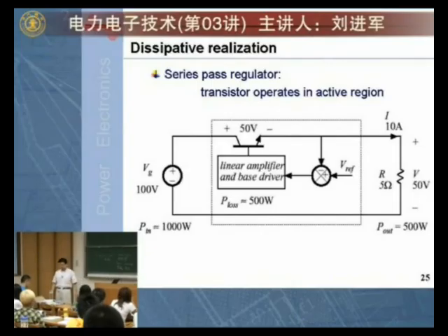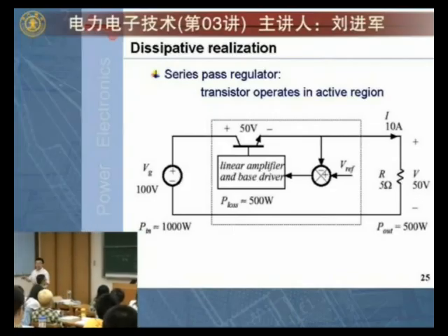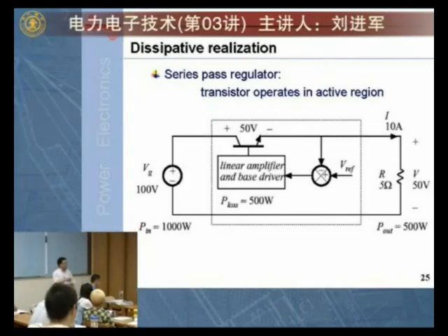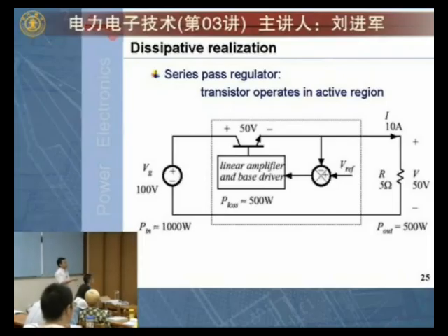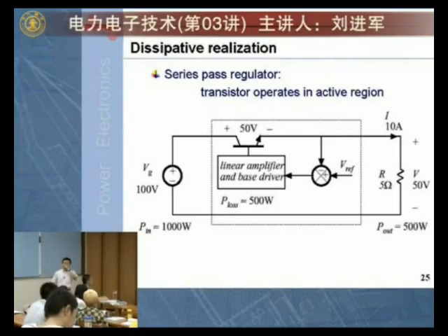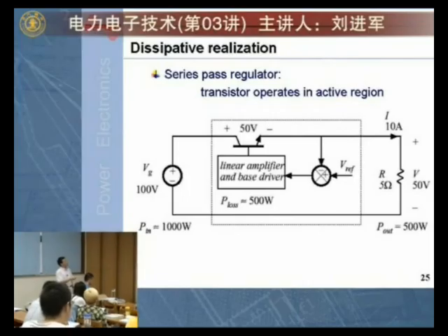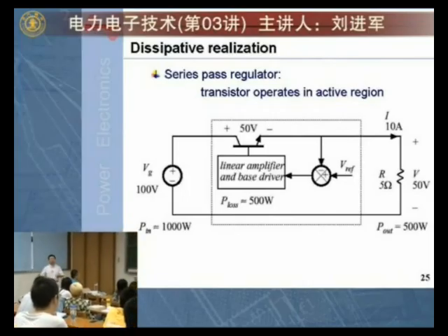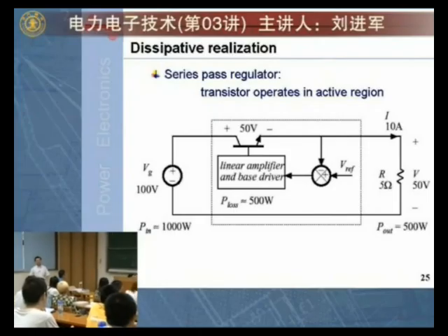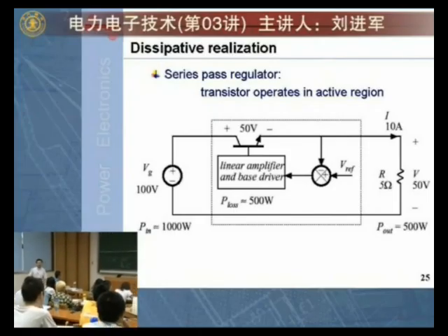Okay, so by the second solution, we can realize automatic control and we can deal with disturbances. Even when this load resistor is changed, and therefore the load voltage is changed, either smaller than 50 volts or higher than 50 volts, even when that happens, I still can measure that and compare with my value of commanding. And therefore, I can change the current flowing through so that I make sure the load voltage is coming back to 50 volts again. So that's exactly how to deal with disturbance.